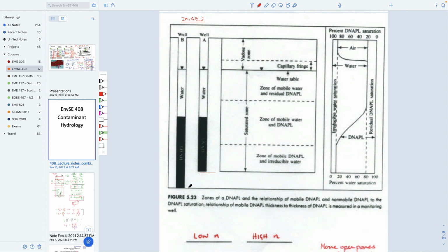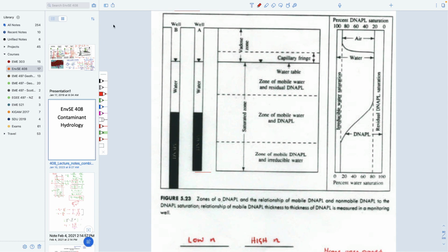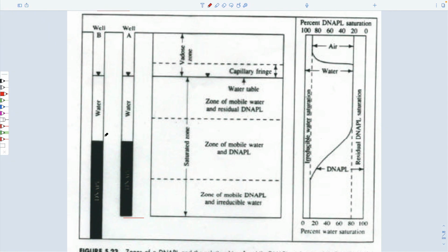But if you keep on drilling, the height of the NAPL that you'll see appears to get longer just because you've got a deeper hole. And all it's responding to is the fact that the free surface for this wants to be here, and as long as there's enough volume in here to flow into here, it'll just keep on going down as long as you drill the hole. And so that's our mindset that we have to understand for this.